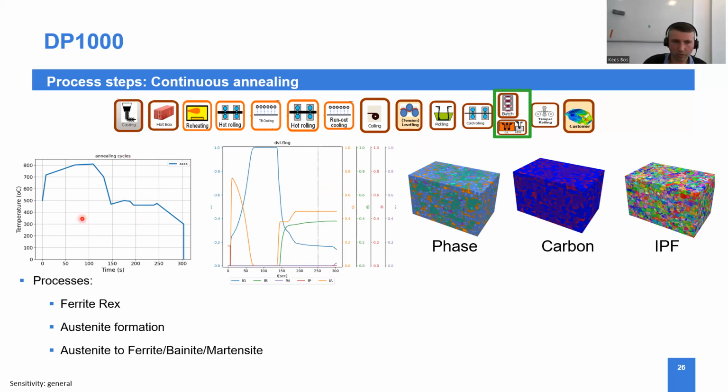So if you really want to know whether this was intercritical annealing, you can... no, it was full annealing actually, because you see here that the austenite phase fraction reaches 100%, and then on cooling the ferrite starts to form again, and we have a major bainite phase, and at the very final quench we have some martensite forming.